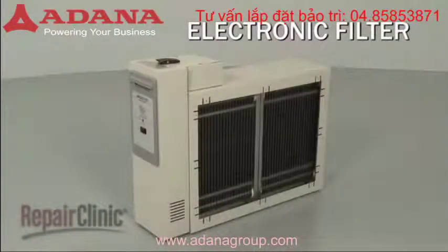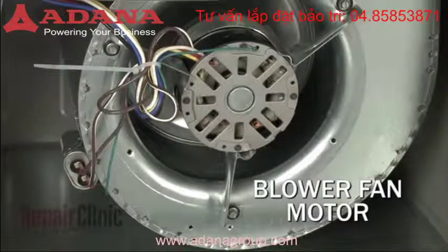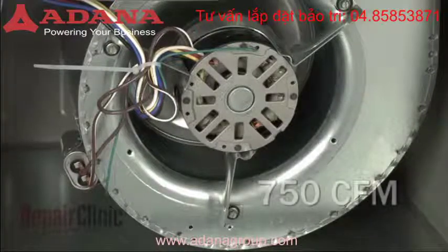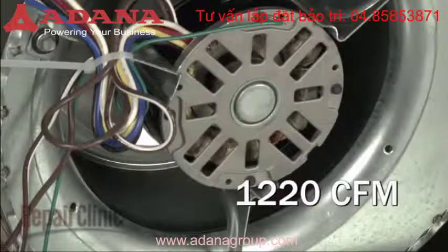Some homes will have an electronic air filter, which is powered by the furnace or air handler control board when the circulation blower fan turns on. The blower fan motor can run at multiple speeds to improve efficiency. Lower speeds are used when the furnace is heating, and higher speeds are used for air conditioning.